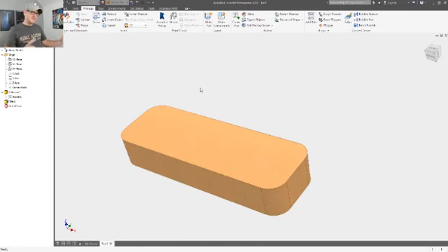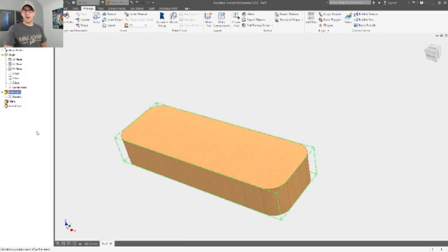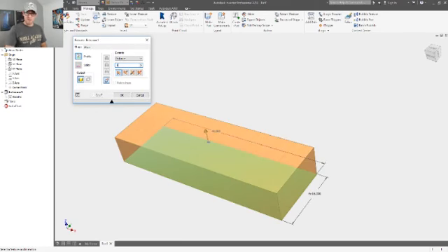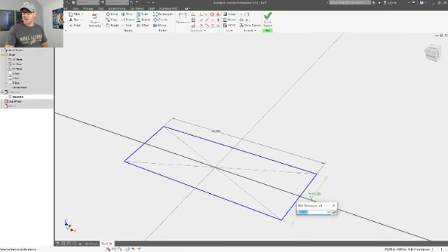And the next thing I wanted to talk about, and this is going to be a short live with Luke, is materials. So let's say this was a piece of wood, and I'm going to edit my feature, and I only want this to be an inch tall, and I don't want my fillets, and I want this sketch here to be 1/4 of that, so by 4.